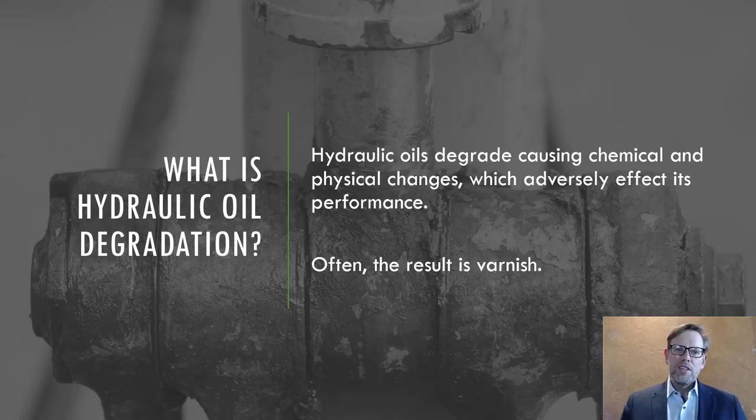Starting off with a couple definitions. Hydraulic oil, I think if you're here, most of you probably know what this is. Basically, it's a fluid, and this medium is used as a way to transfer power from one place to another in a hydraulic system. How they degrade is that even before they actually go into service, there is a chance that hydraulic oil may start degrading, just sitting in drums before it actually goes in your system.